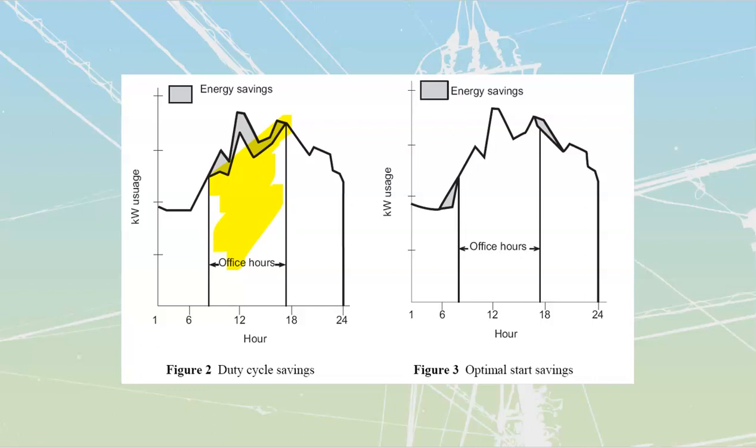Examples of these are going to be heat or other things that they carry through, but we don't necessarily need to have them on all the time. Some ventilation fans and stuff like that. If you're still getting your proper cubic feet per minute that you're pulling out of a building, you're going to shut some of them down, then you're going to turn them on and move the air again, shut some down, turn on and move the air again, etc. So it's just going to be an on-off where we are shedding some of our load through that.